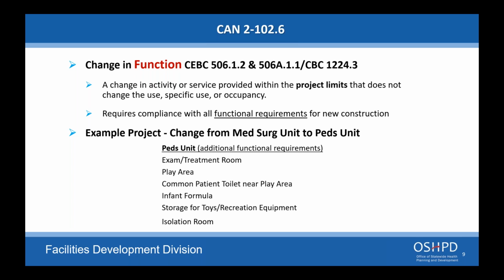If you have issues for exhaust pipe locations that are non-compliant with the current code, but they are compliant with a previous version of the code, that is okay. Again, if you're just doing an equipment replacement on this generator, we're not going to make you relocate it, because now it is no longer an equipment replacement. But there are things that you need to be aware of. And yes, you do have to meet current requirements for anchorage and so forth.